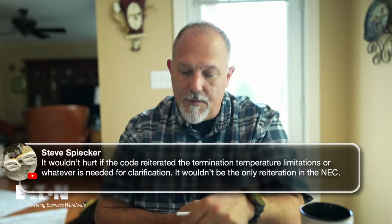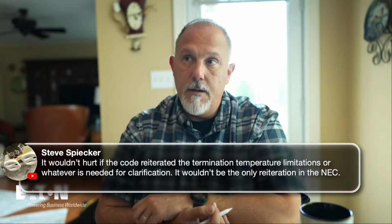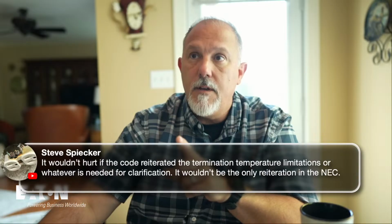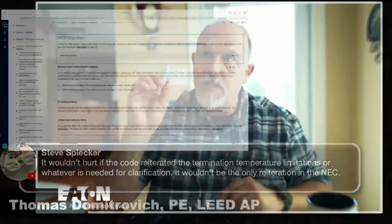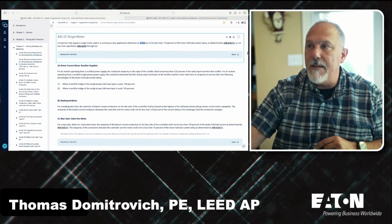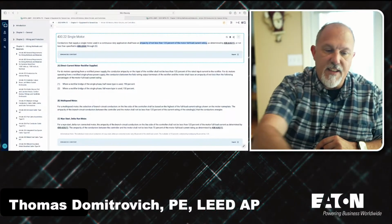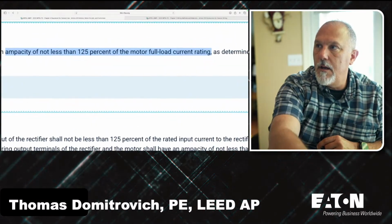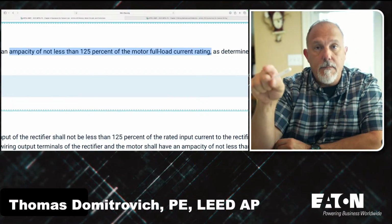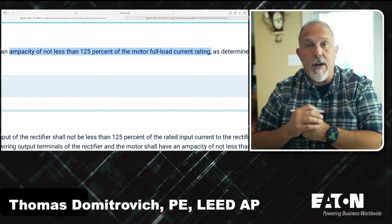And it may require that I increase that number 12 to a larger conductor, because the only thing that 430.22 is telling me is the ampacity must not be less than 125% of the full load current rating. It doesn't tell me that's what it's got to be. I could have to go larger for a few different reasons. Voltage drop might be one of them.